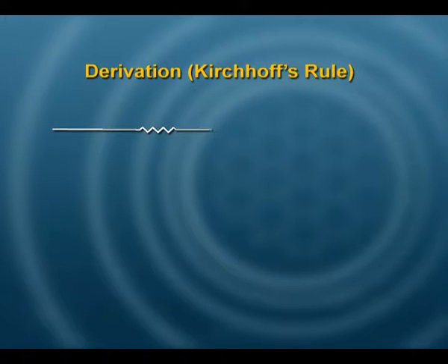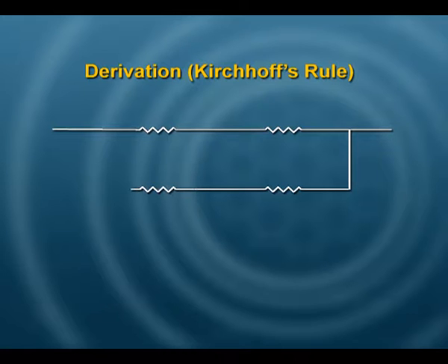Now, we are going to see how we can use Kirchoff's rules for electrical circuits to find a condition for resistances for a balanced Wheatstone bridge. Let us see what our Wheatstone bridge looks like. It must have 4 resistances, with a pair placed in series and the pairs placed in parallel. If I mark these P, Q, R, S, according to Wheatstone bridge, a balanced bridge would happen if I have